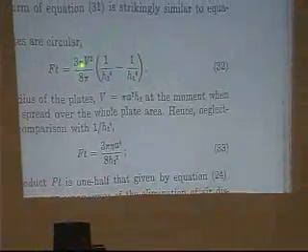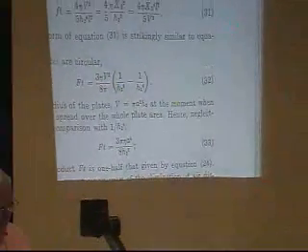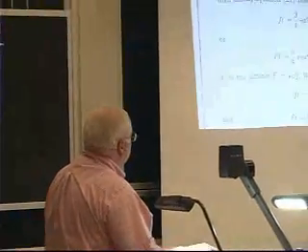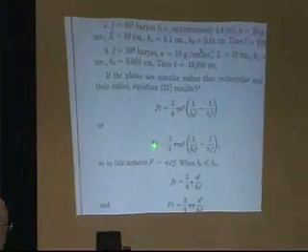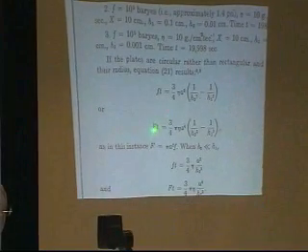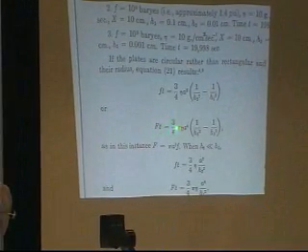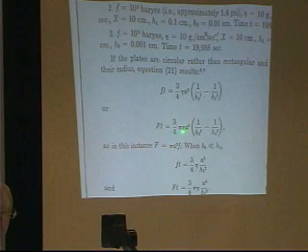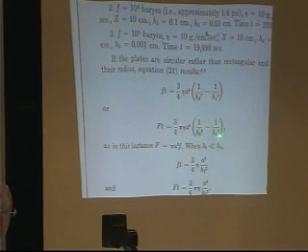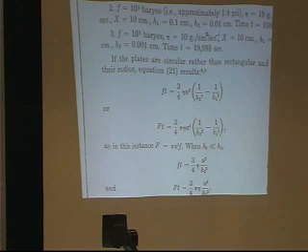Raised to the 4th power, you got viscosity in here, and you got a v squared. The formula that I actually gave you in the book, he goes through some other machinations, or in chapter 16, is the force time product. We're talking about a kinetic process, so we're worried about time. The force to squeeze these together times time is 3/4 pi viscosity A, which is the radius of the circular disc, times 1 over h2 minus 1 over h1 squared. And this is all in chapter 16.